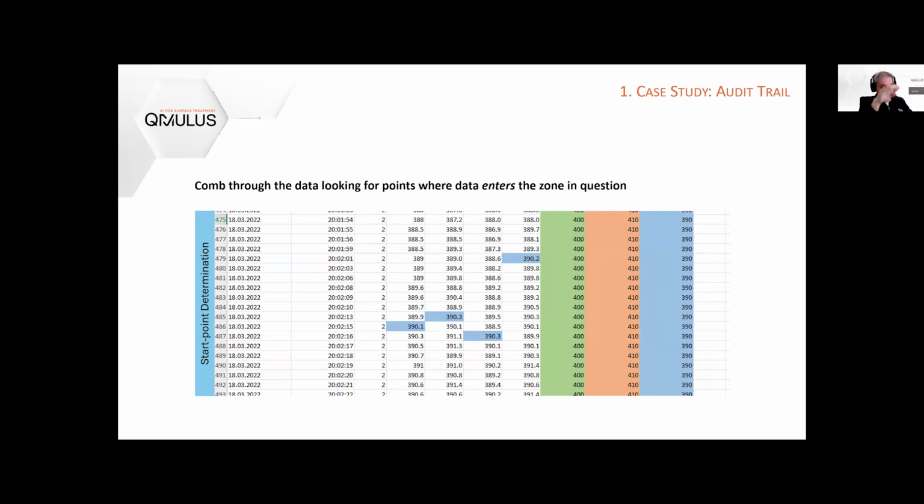And I scroll down the temperature and I look at the main TC, TC1, TC2, whatever thermocouples may have been connected or required to be connected. I scroll down, page down, page down, page down, see the temperature rise: 100, 200, 300, and then 390.1. And my minimum was 390. Great. So I highlight, like if this were paper, I would have highlighted with a highlighter. So the thermocouple came in at this time. And of course, I should not exceed 410, right?